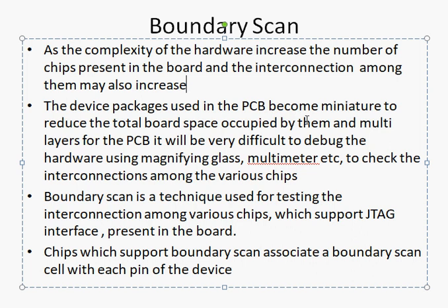So when the circuit size is very small, a new methodology is needed to figure out whether there are any issues with the ICs in your motherboard. For that purpose we use the concept of boundary scan. Boundary scan is a technique used for testing the interconnection among various chips.